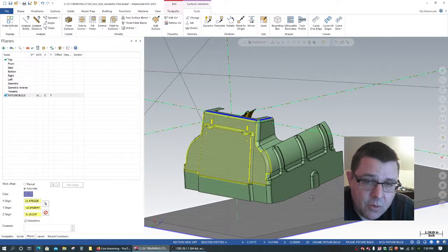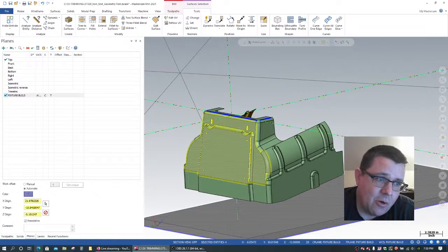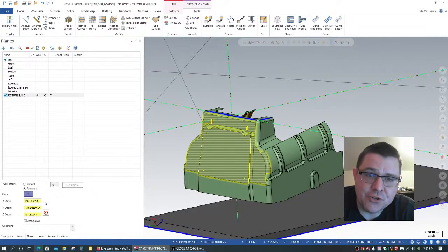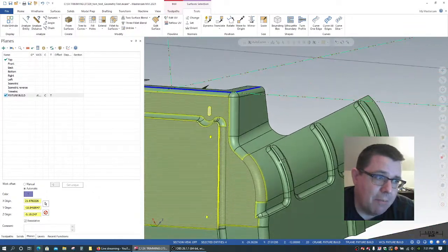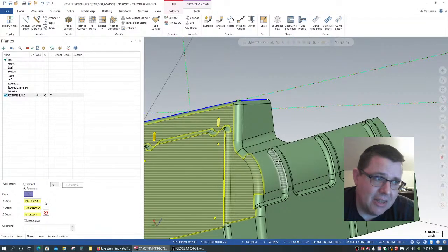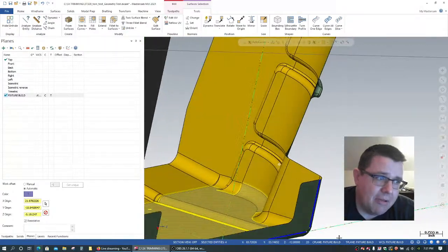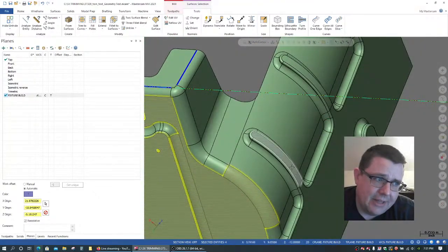Because I may use some of those actual surfaces themselves, but typically what I'm going to do is take some wireframe, project it down, build a flat profile, extrude it, and then start chopping away some features of it to build my own solid so that I can control all the features. Because I may not want to put a whole lot of detail in this. Like, on my vacuum fixture, would I machine in all of these fillet surfaces?